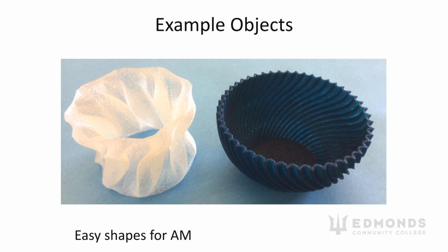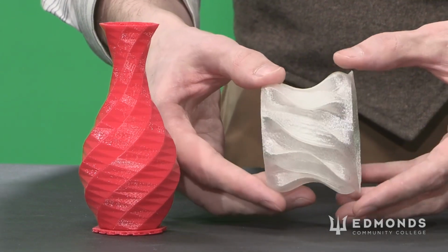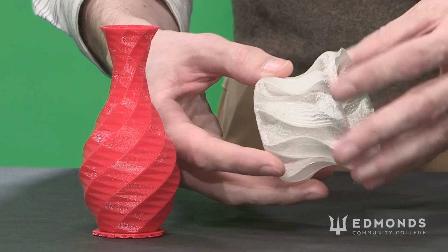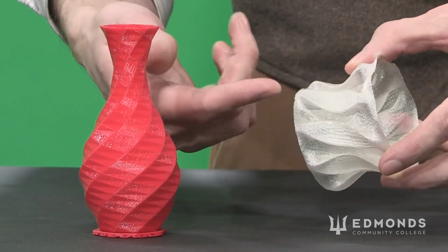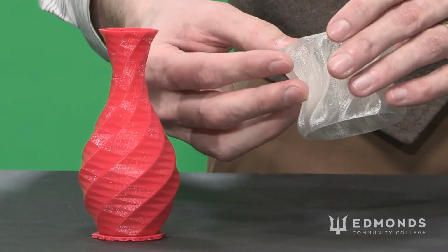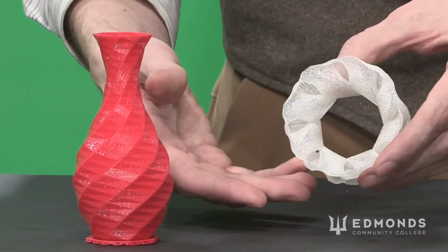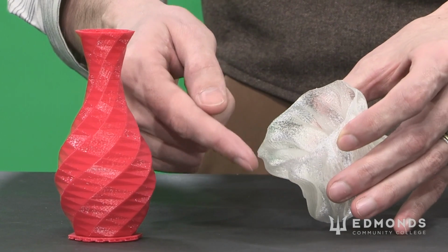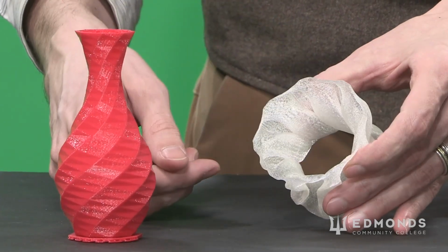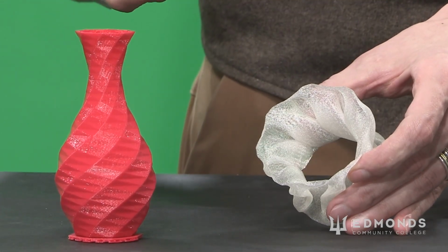So every time the tip has to pick up, stop extruding, or change temperature, that adds extra time to our print. However, even though this kind of folded shape right here would be extremely difficult for us to machine out, or perhaps nearly impossible for us to injection mold, it's extremely easy for additive manufacturing to produce simply by extruding each layer continuously and then moving up one layer.